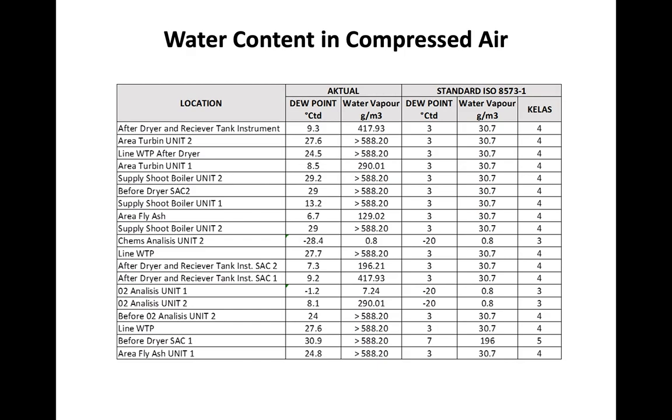In our case, we have measured at more than 20 locations, more than 20 points, to measure dew point, water vapor, and also particle content. But we don't measure the oil content because the type of compressed air installed in this plant is a centrifugal compressor.